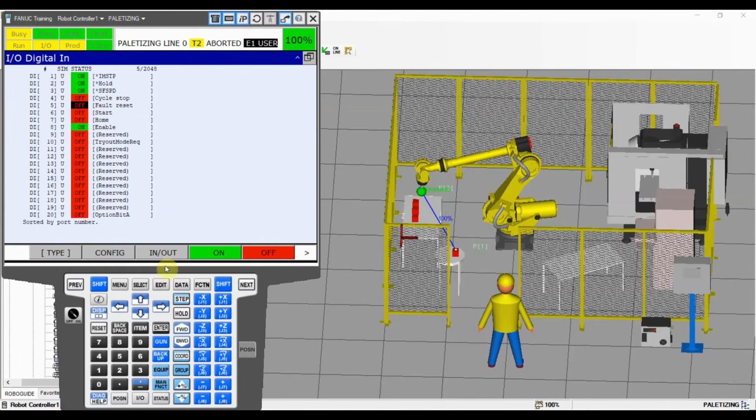And I wanted to tell you a little bit more about simulating. Because the inputs you're getting are something that you can only receive, you cannot send, that means you cannot change the state of it. But there is a way in FANUC to do it, and that's called simulating. So you're going to simulate that input is on or off, so you can run the robot sequence without using the PLC or without getting the feedback from the devices. How do we do that?